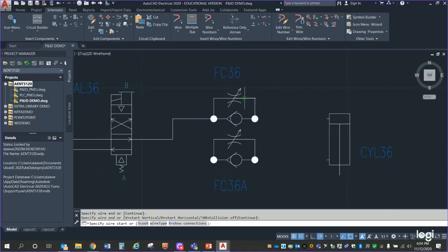The only difference, though, is look what it's drawing. It's drawing kind of an hourglass shape, right? So what that's saying is it can press in and restrict flow, or it can open up more and allow flow. That's what that flow control does. Now, what Andrew was saying is, right now, look at the direction of the arrow. The direction of the arrow is going to come in, but none of the air is going to go through that restricting plate. Why? Because the check valve is going to allow full flow.